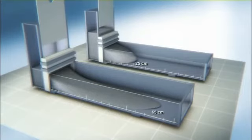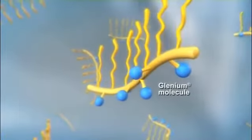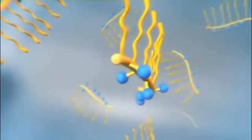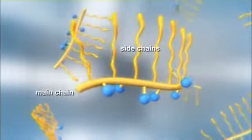Modern superplasticizers like glenium are based on synthetic organic polymers such as polycarboxylate ether, called PCE for short. A PCE molecule consists of one long main chain and shorter side chains. The main chains are negatively charged.